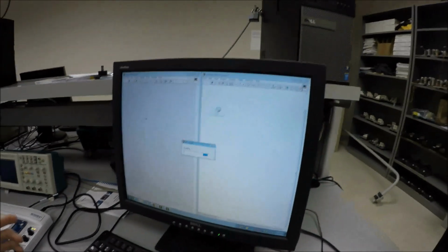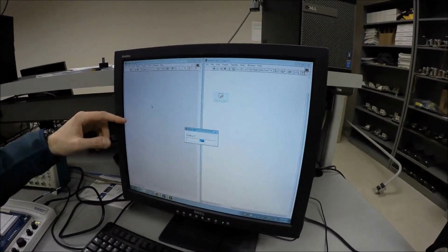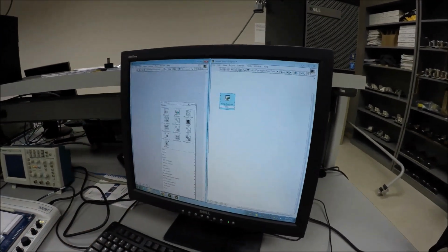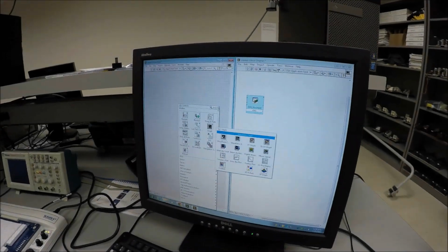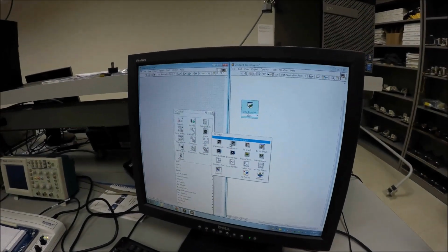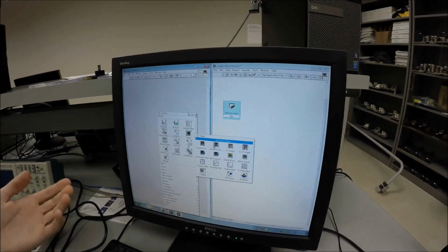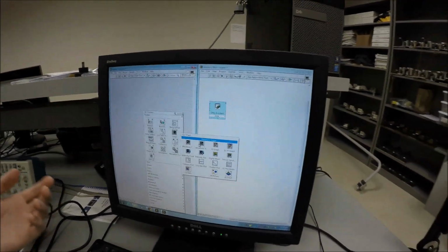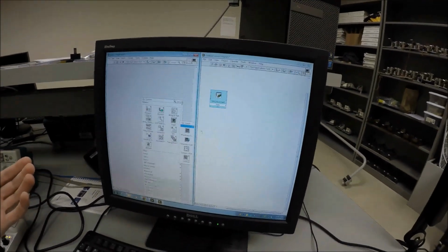It'll initialize everything. Then in the front panel, what we'll do once this is finished is we'll right-click, and go to Graph. So we have Waveform Chart and Waveform Graph, the two that we'll use. Waveform chart you typically will use when you have a loop. In this case, we don't have a loop, so we'll use a waveform graph.